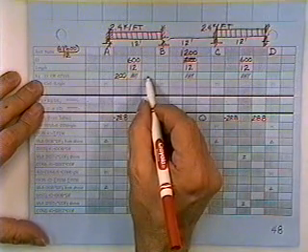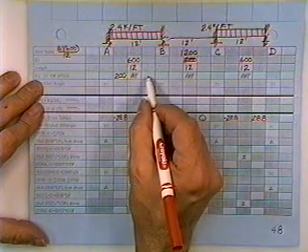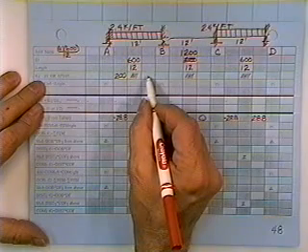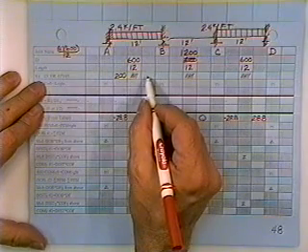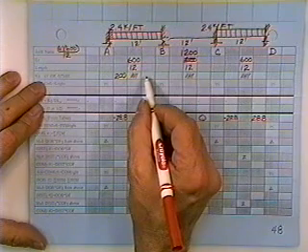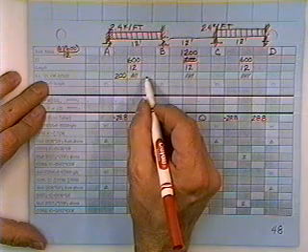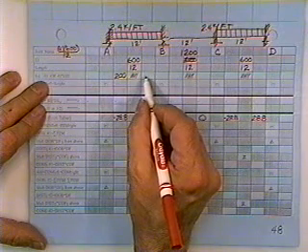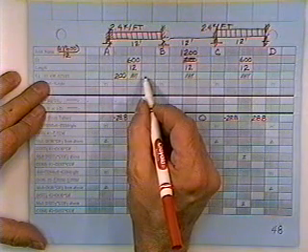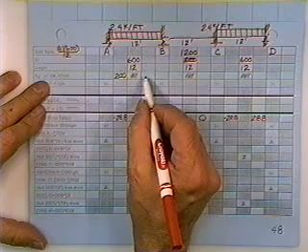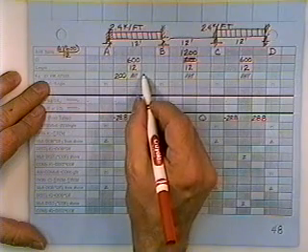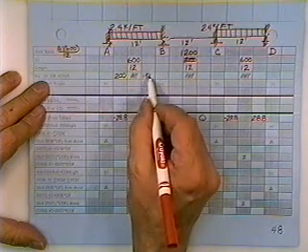Because when I get down here to the left of joint B and look to the left, I do see a pin, and I see nothing past that pin. Therefore the answer should be 3EI over L because of what I see on the other end of the beam. 3EI over L would be 3/12 of 600. That should be 150.